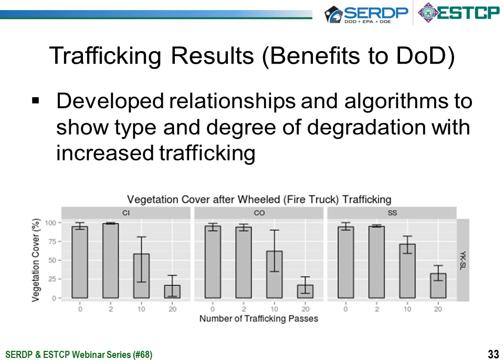Similar statistical and comparative analysis is presented in the final report for all the soil, vegetation, and laboratory measured surface emission data collected. Decay function algorithms were developed from this type of data, which can be incorporated directly into other models to represent the loss of vegetation cover with increasing number of vehicle passes. Likewise, similar response functions were also developed for loss of vegetation mass and the compaction effects due to the military pass trafficking as well.